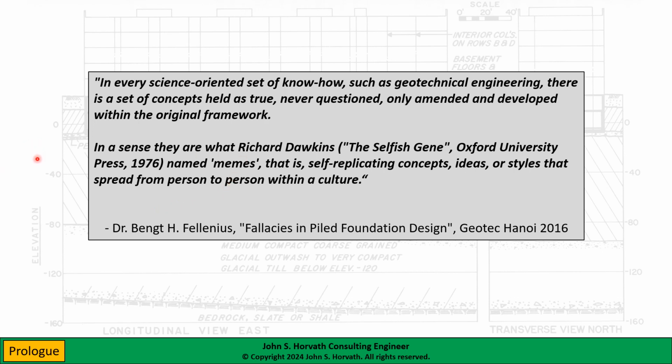Now, the meme that Fellenius was talking about is the way that we design deep foundation elements for axial compressive loads. Just about everybody believes that piles or some type of drilled element should be designed based on soil strength and the geotechnical ultimate limit state. And it turns out that's simply incorrect.